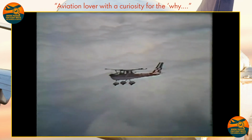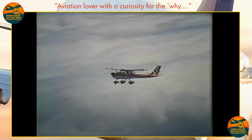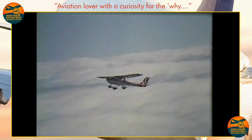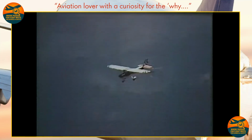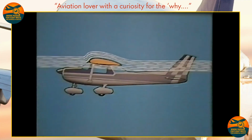The stall can be demonstrated in the air. The angle of attack is increased until it becomes critical. Lift is suddenly reduced. The aeroplane drops, pitching nose down, and quite a lot of height is lost before normal, controlled flight can be resumed. This can only happen when the relative airflow over the wing regains its normal angle and lift is restored.